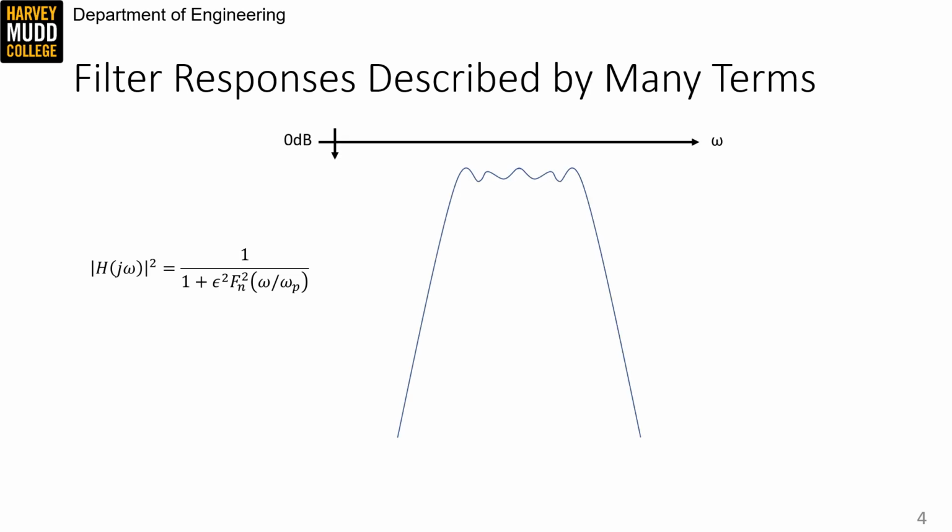This is the general picture of what that transfer function might look like. You can see that the x-axis indicates the filter behavior changes with frequency, and the y-axis has units of dB, which means that we're framing our discussion in terms of how much power gets through a filter. That's consistent with the picture painted by our equation, which represents a transfer function squared and accordingly describes a ratio of powers rather than a ratio of voltages or currents.